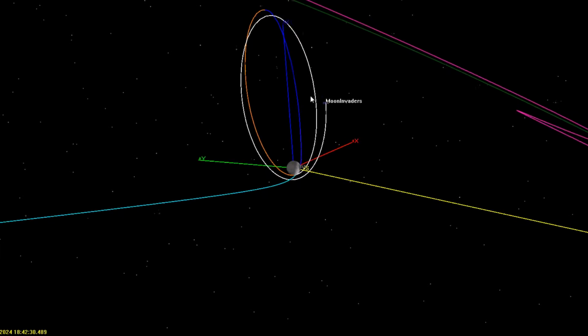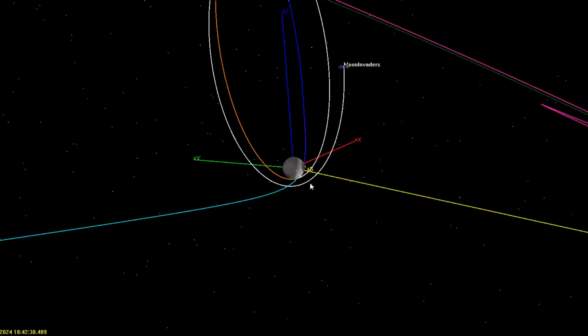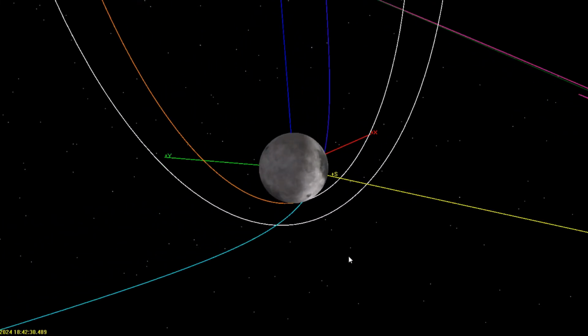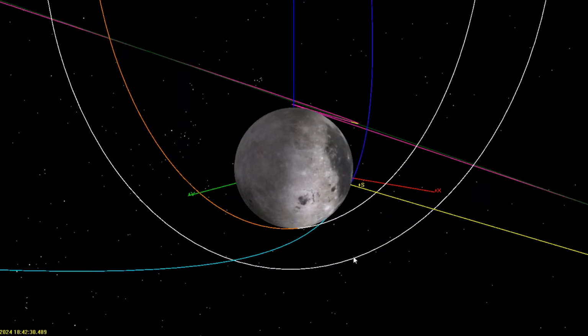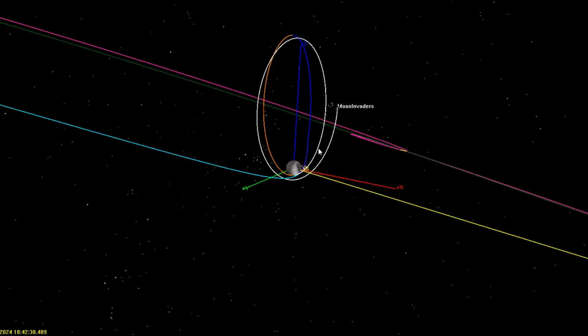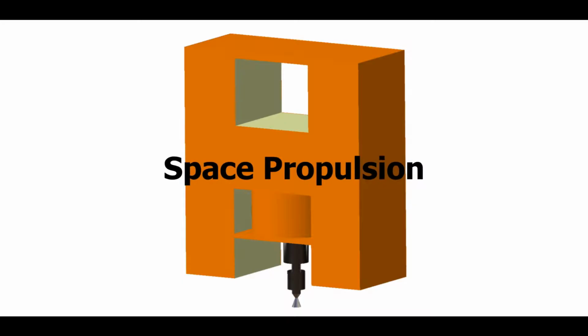Afterwards, reaching the orbit's apoapsis, we'll perform a very small burn to adjust periapsis to a height above about 20 kilometers. The second flyby will be closer and on a different location above the south pole, like in here, shown in orange. Following the second flyby, the spacecraft will transmit the data again and remain on the Moon's orbit with a minimal amount of fuel, so it's possible to obtain new data if needed.